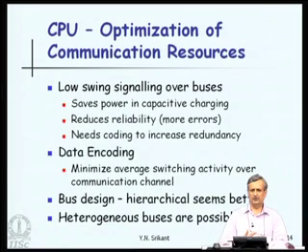Okay. So, low swing signaling over buses. That means if the bus is switching between 1 and 0, anyway all transmissions are digital, the high may rise to something like 2 volts or 3 volts or 1 volt depending on the power supply, and the low can be maybe 0 or negative.